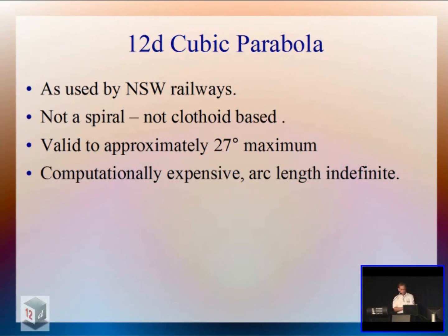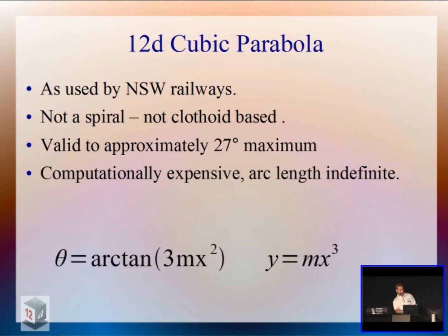Surprisingly, these cubic parabolas are computationally quite expensive because while we have a deflection angle defined, which is very simple, you'll notice in the little other formula, y equals mx cubed, we don't have any specific relationship with the arc length to the values that we need to set out. So we actually have to do an iterative solution to do it.